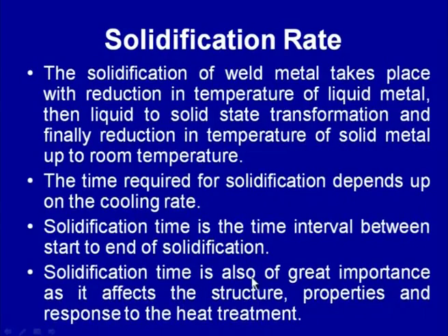So, coarse grain structures respond slowly to austenitizing and solutionizing, while in case of higher cooling rates, when the solidification time is less, a finer grain structure is obtained, which in turn results in better mechanical properties and better response to heat treatment.